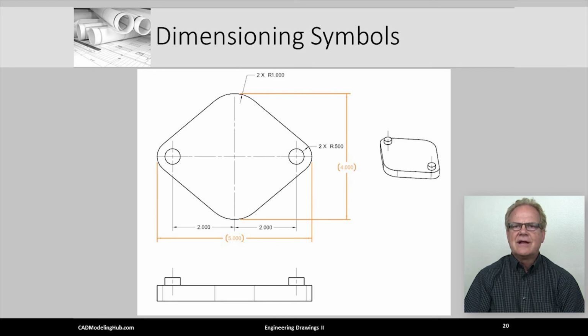This is an example of using reference dimensions to indicate the approximate size of this quadrilateral object. To include either or both of these reference dimensions without putting parentheses around them would have caused this object to be over-dimensioned.